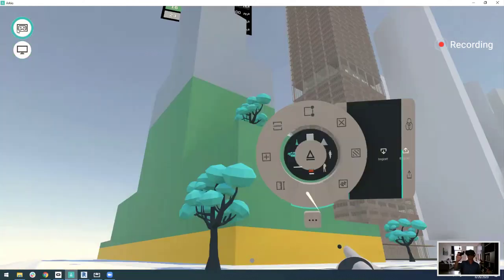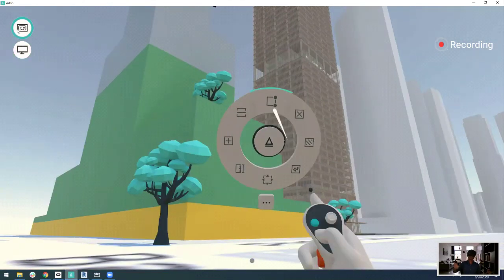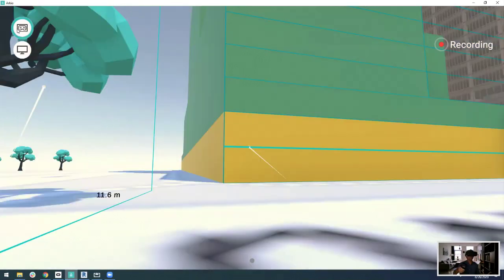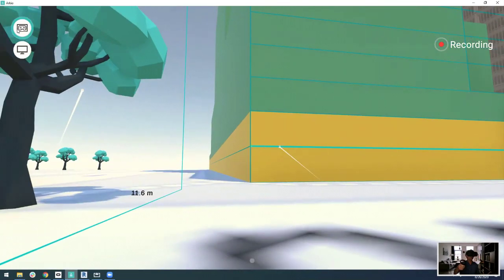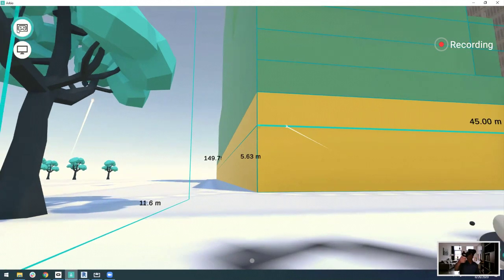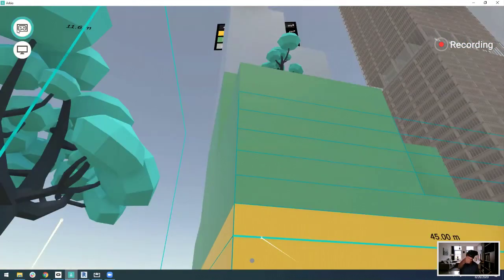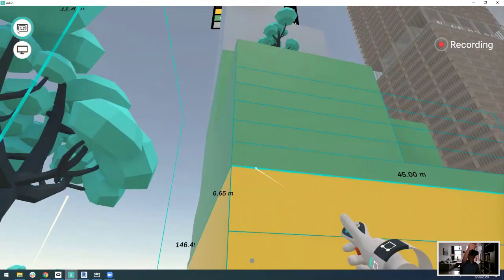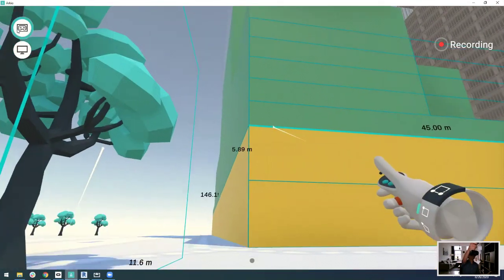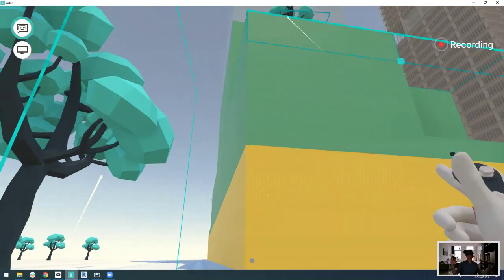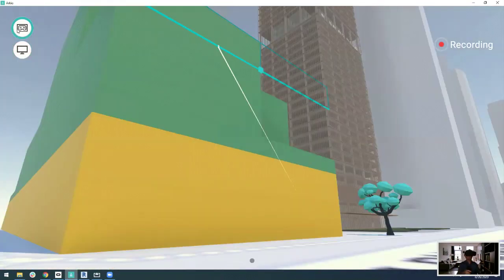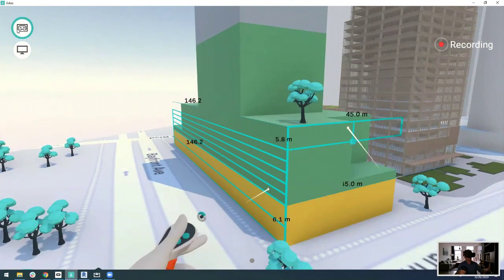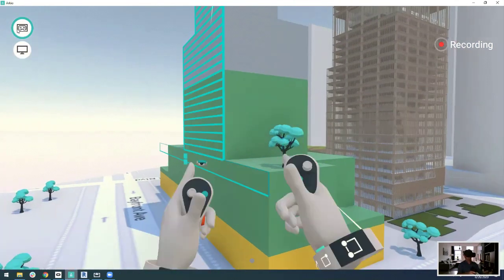But on this level, I'm still able to make adjustments. So maybe I want to make those first 2 levels, I don't want to make them 3 meters high. I want to make them 6 meters high. And you see when I'm doing that, it stretches the tower top geometry with it. So everything is connected and parametrically aligned. And it works a bit like the meshing tool in Revit and FormIt, but we try to make things a bit more like physical model making.